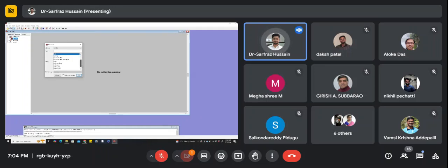And if you want to directly export the netlist, you can go for this netlist. You can see there are a lot of views, so you can use a lot of things. Now the default technology that we are using is MOS-CMOS. So this default technology, let it be. But later on we'll call upon the GF180. I'll show how to call that one.